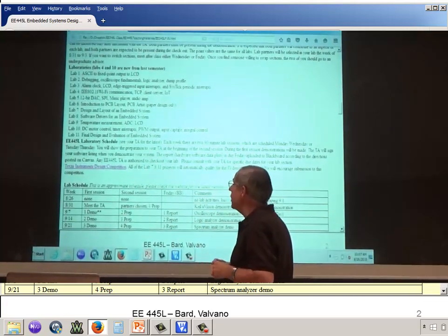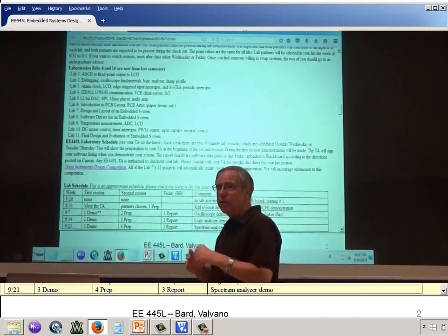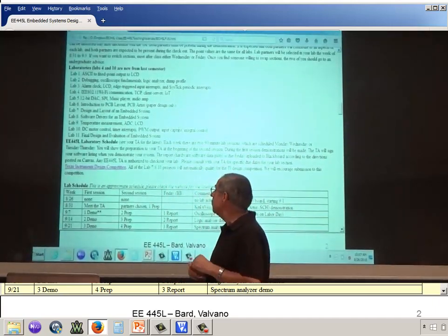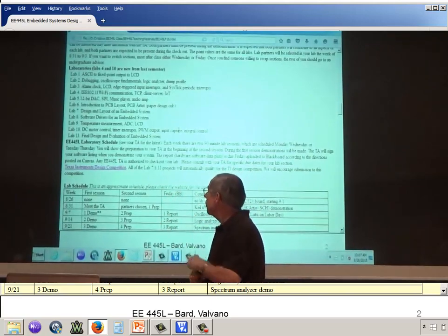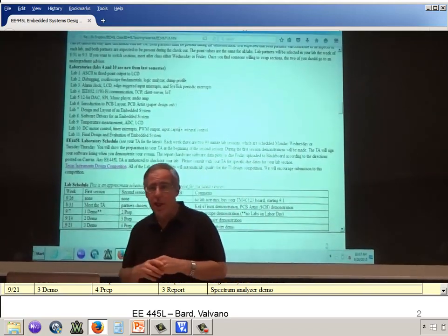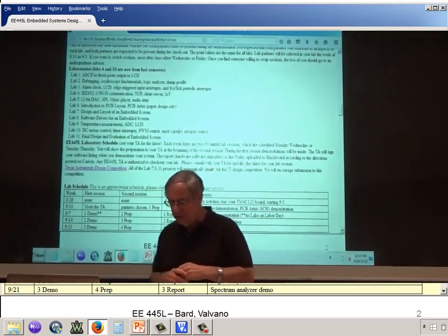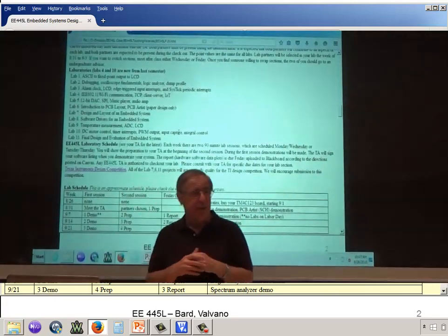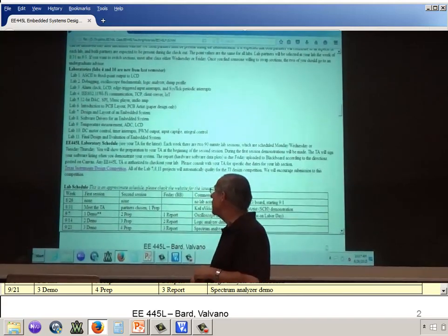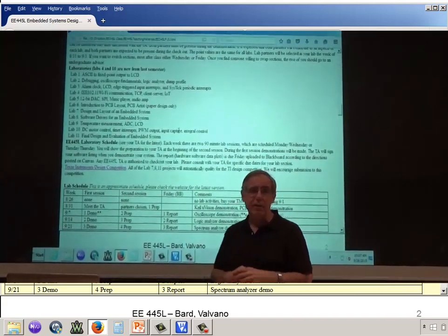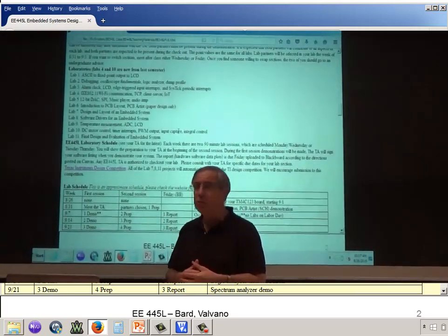Then we'll go back in 9 and 10 and get some more basic interfacing, an embedded system making a thermometer and controlling a motor. We'll spin a motor, and we won't use the D term of the PID controller because it's highly unstable and we got crappy sensors, but we'll use a PI. So that's essentially, if you look at what you will learn, it's what you do.